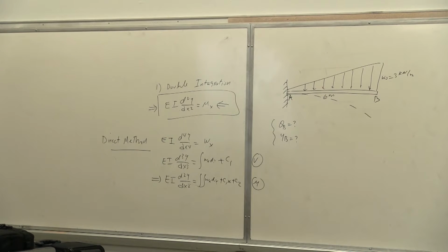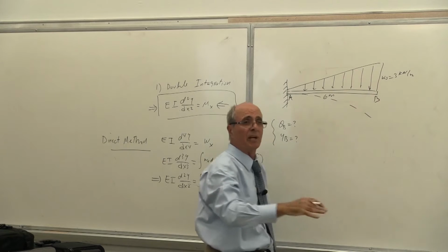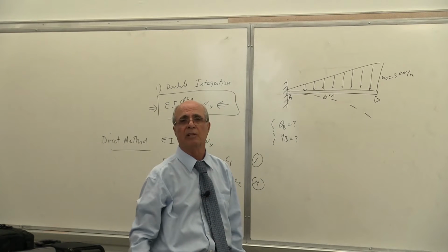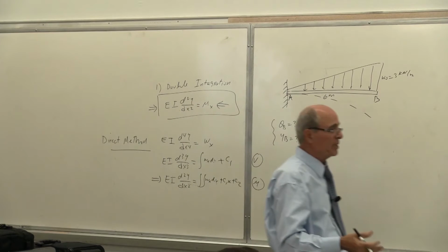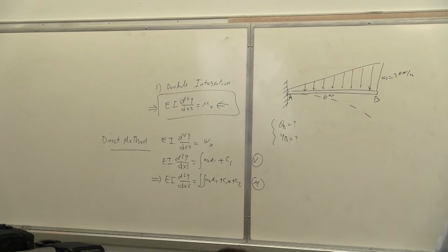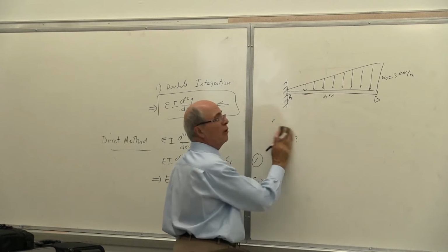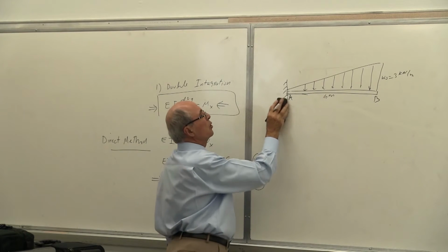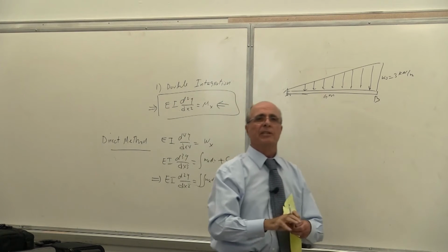All right, now double integration. In double integration, you have to be careful here. I have given this problem before. You have a couple of problems like that, which start like a triangle, problem number 9 or 10, I don't know. But students generally have a problem with the statics. First of all, like every other problem, the first thing we do is find the reactions. So you remove the supports and replace them with appropriate reactions.